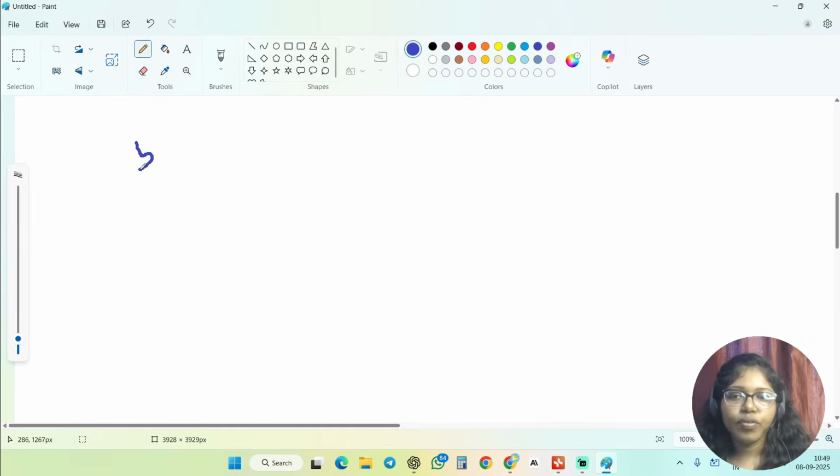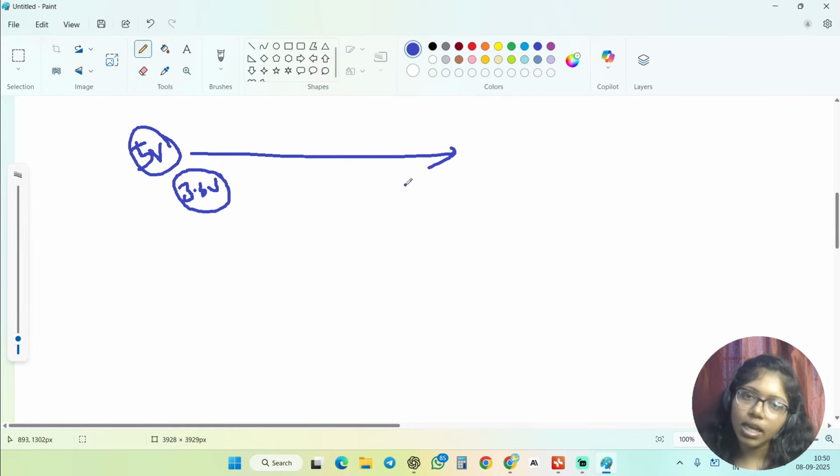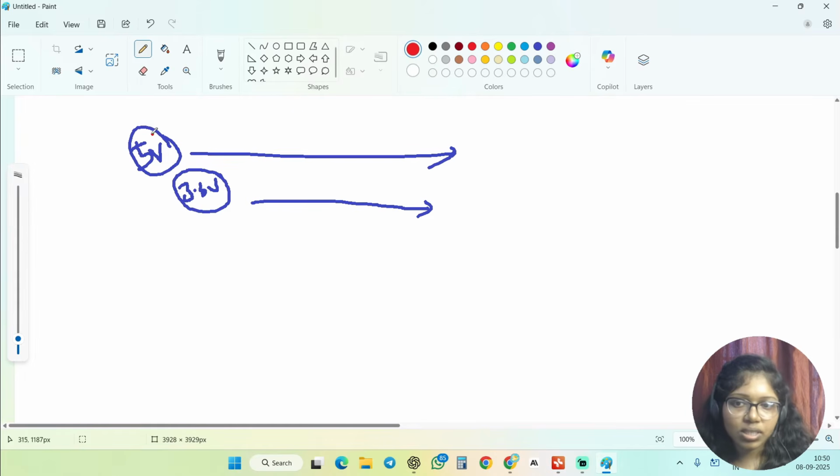If your microcontroller has 5 volt or 3.3 volt, you can only give 5 volt to any of the peripherals. If you have 3.3 volt, you can only give 3.3 volt. You can't reduce it directly from the microcontroller. If you want to reduce the value, you can use a resistor here to drop some voltage, and then you can apply it to the LED.